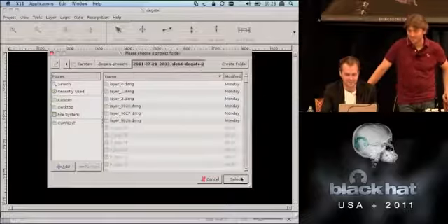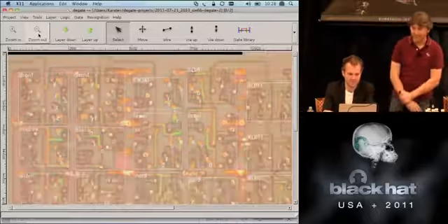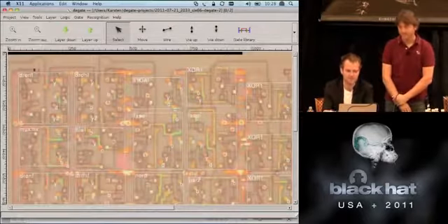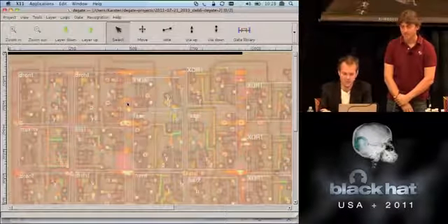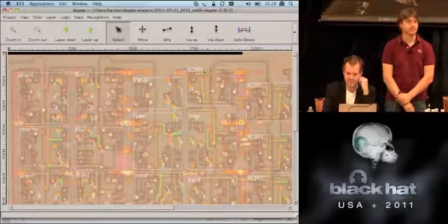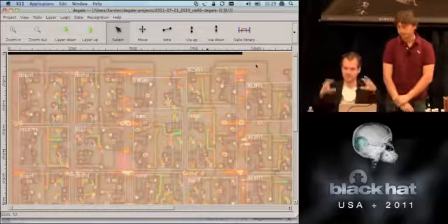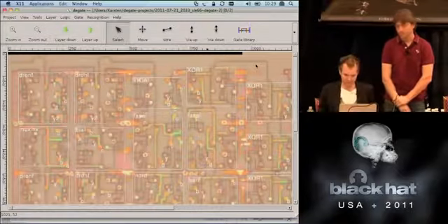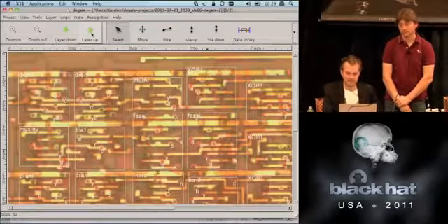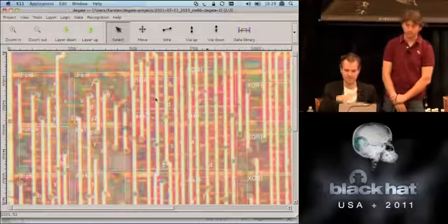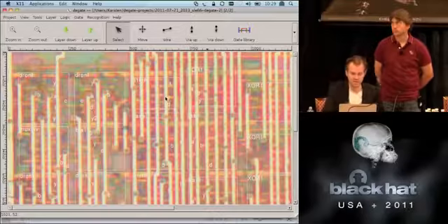So, for instance, this is a small part of this memory decryption function we reversed, and this is already showing the gate instantiation. A gate will be a functional unit, for instance, an XOR, right? So here's an XOR, here's another XOR, placed on a 2D map of functions, and then, as we were saying before, there are metal wires connecting these, and there are several layers of these. In this case, only two for the metal, and there are others on top for bigger routing, I think.